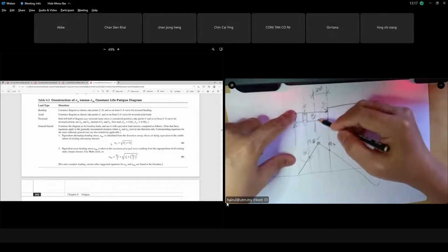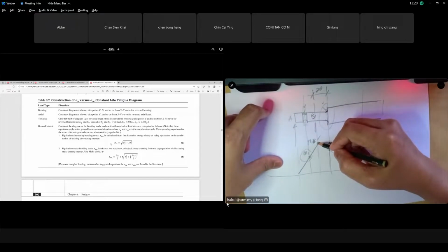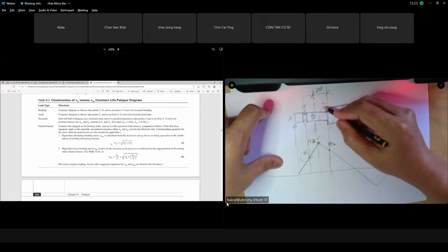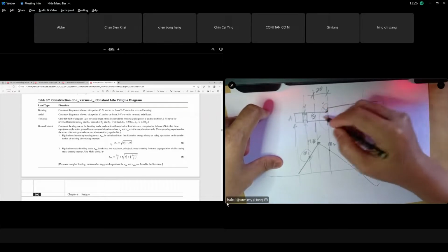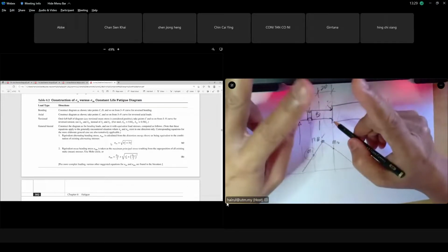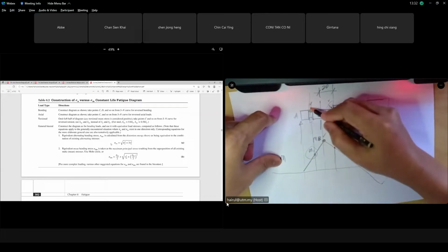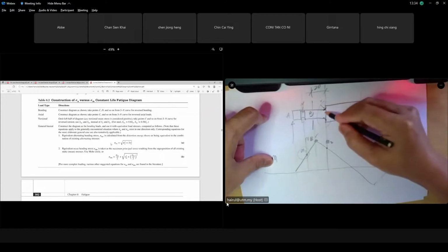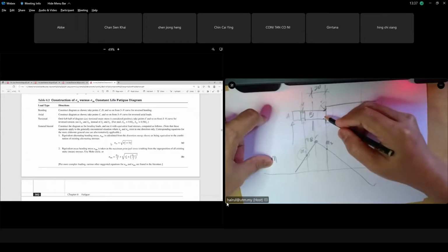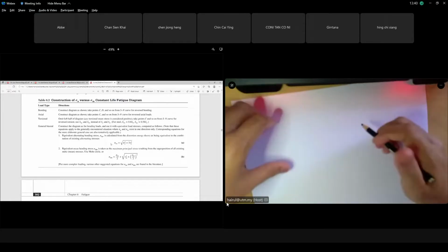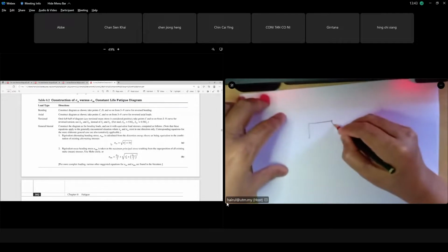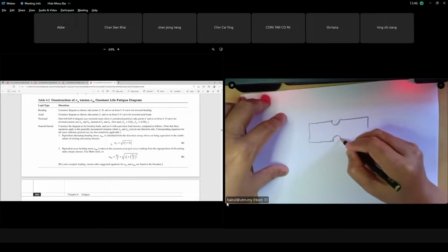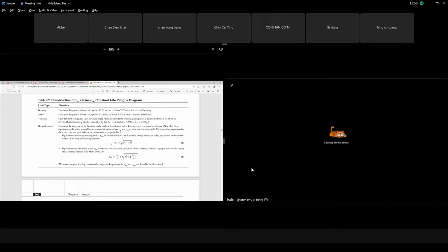Actually, even though your maximum moment is at B, the weakest point along your shaft is at the shoulder, because we have a fillet radius here and also a notch radius. So we have 2 points to consider: at M1, where we have a groove, and here at the shoulder, where we have a fillet. That is what we call stress concentration. For example, if your shaft is not just a plain diameter but has a groove, where we put a washer or snap fit ring to lock the pulley so it does not misalign.